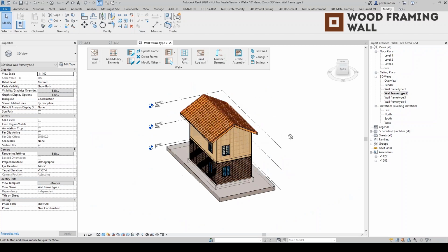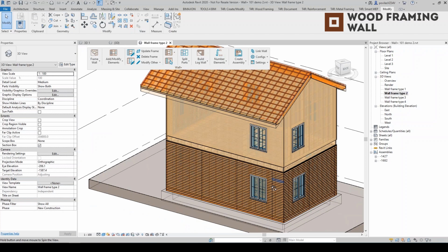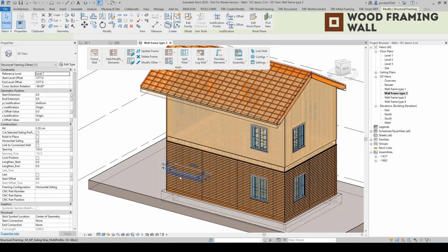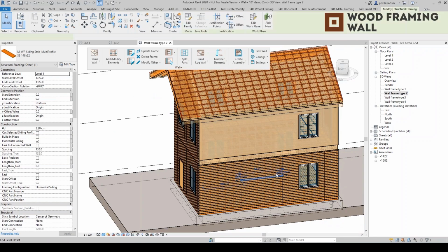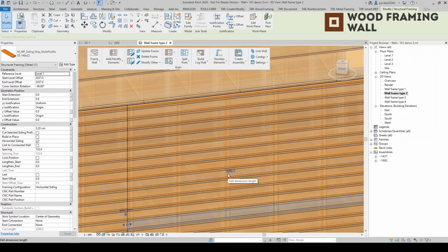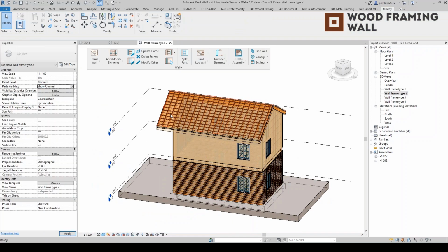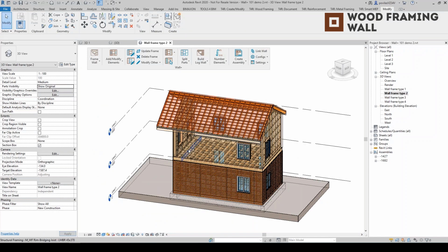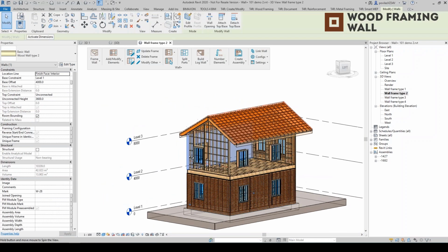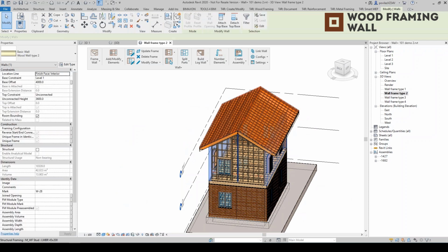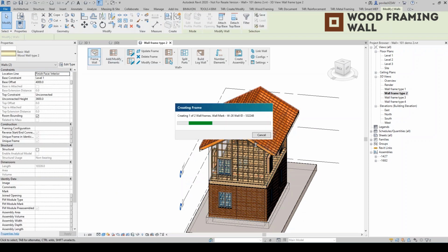Okay, in this case we have horizontal siding, timber boards. Okay, perhaps I can see 3.2 meters, I think. So again, first off, switch to original, and then we have a few walls that are left unframed. If I select those two walls and add main frame.